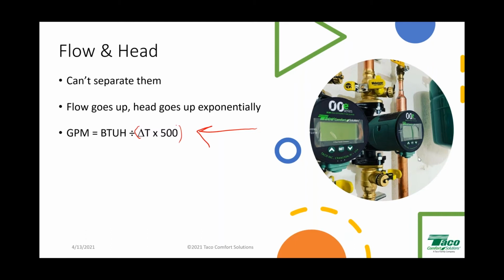in an hour, that is traditionally 60, times the specific gravity of the fluid. 100% water has a specific gravity of 1, times the specific heat of the fluid. 100% water has a specific heat of 1. 8.33 times 60 times 1 is 499.8. We'll call it 500.